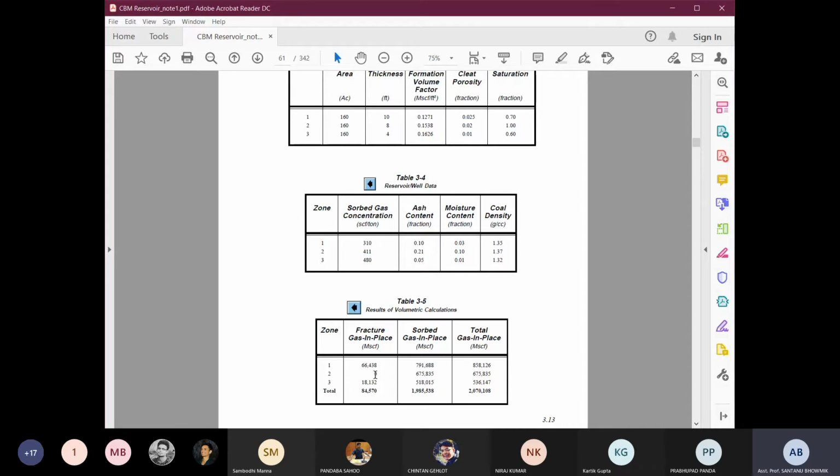So what will happen? The borehole is going to be connected with the surface, which is open at atmospheric pressure. So the moment your fracture connects with the borehole, the gases present there are going to be reduced directly to atmospheric pressure. Whenever it is reduced to atmospheric pressure, the gas will soon escape.